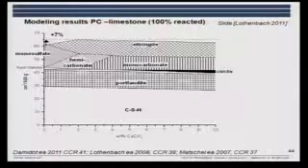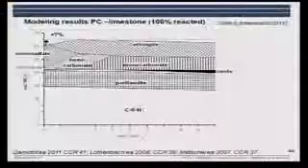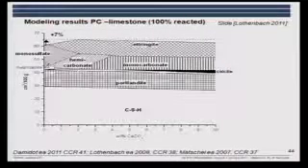This is an example of how this thermodynamic modeling can be used. And here you see the impact of the limestone filler on the phases in the system with the Portland cement. It's assumed that we have full reaction. So what you see is that at a certain time, initially, if we don't have the limestone, we have some monosulfate.